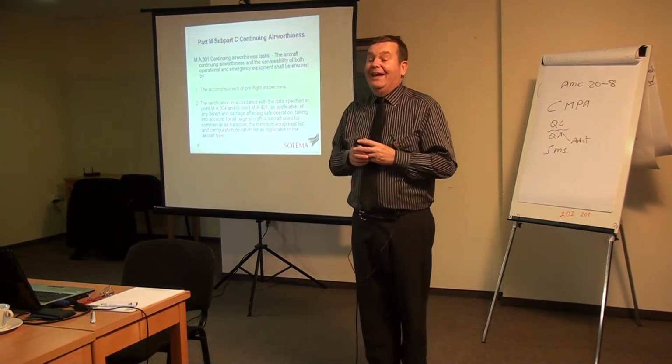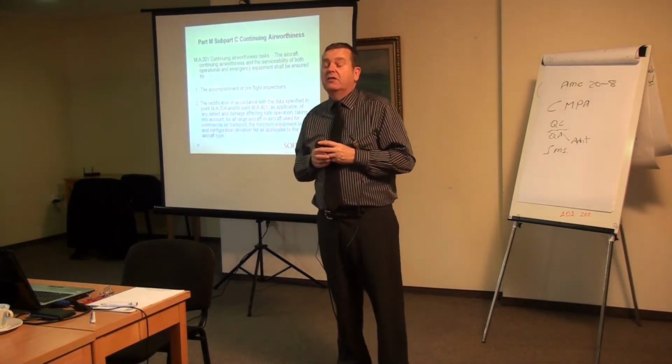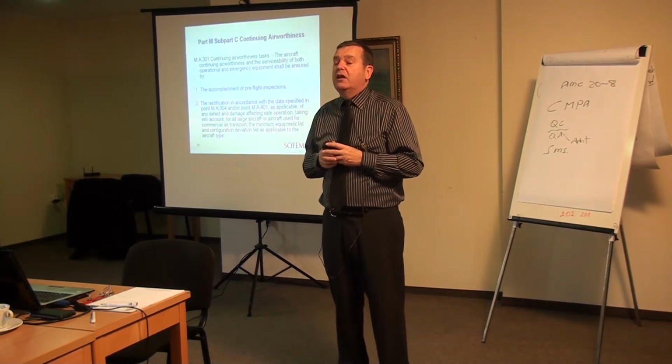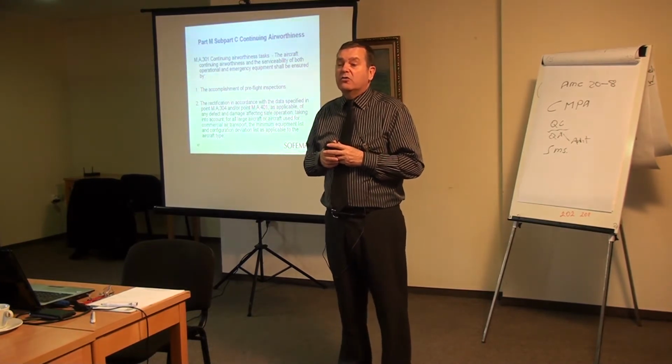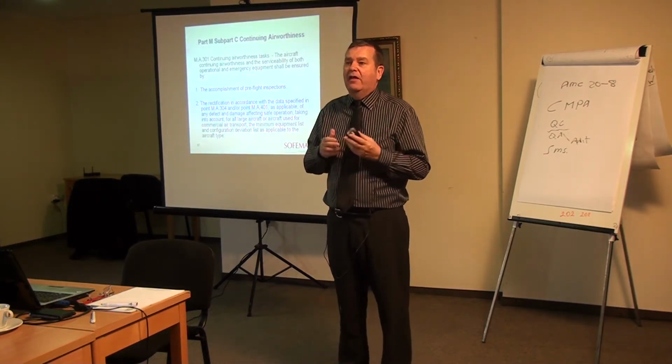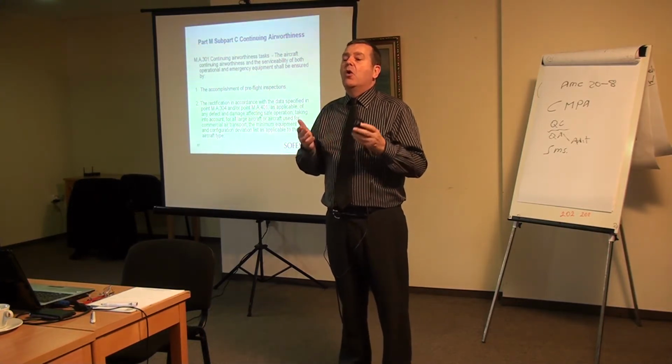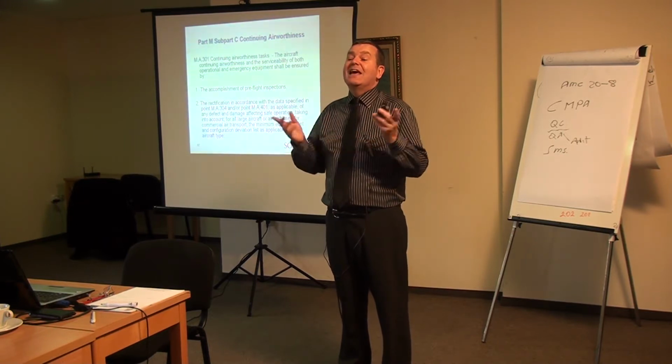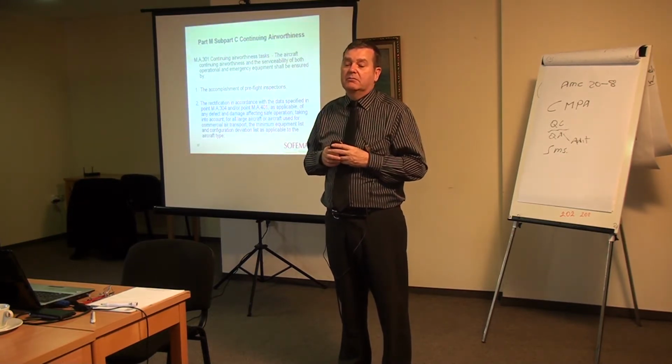What do we look at? It depends on the aircraft, but typically we're looking to see that all the panels are closed, that the engines are closed, that the aircraft configuration is correct, and that, for example, no safety equipment is left external to the airplane.